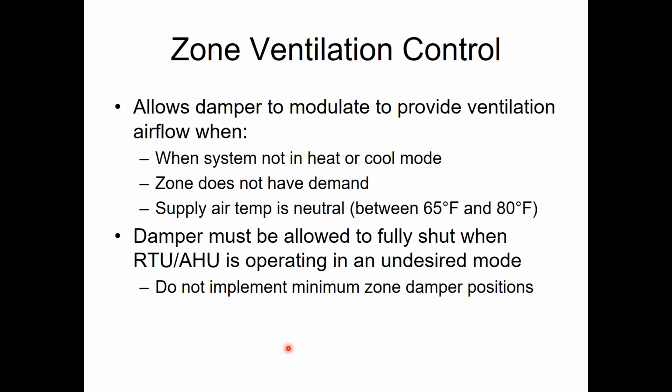But you cannot, at any point in time, let 100-degree air go into a zone that wants cooling. So when your system's in heating mode, if you got somebody that wants cooling, you have to shut the damper. If you don't do it, you will have a nightmare of a job that will never, ever have satisfied occupants. But Ryan, you're the code guy. You love complying with code. Yes, I'm telling you, you have to stop complying with the ventilation code if you want to have a VVT system that has zones that want heating and cooling at the same time.